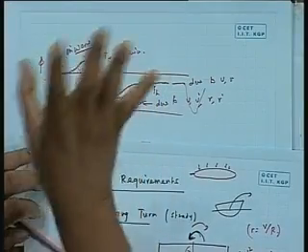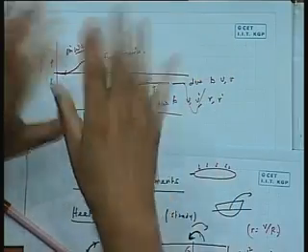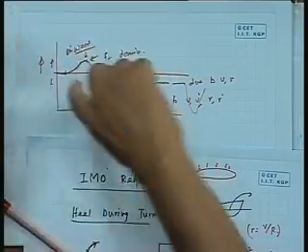So when the rudder is brought to zero in the moment of turning, FH will try to heel it the other way. Because initially you have no FH, only FR, so it is turning inward. Then eventually FH becomes more, like the diagram we showed. Same rudder position, the rudder is already finished here. Say you want to make a port turn or starboard turn, so you have given a rudder accordingly on this side.